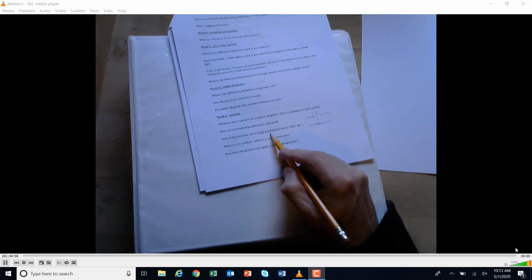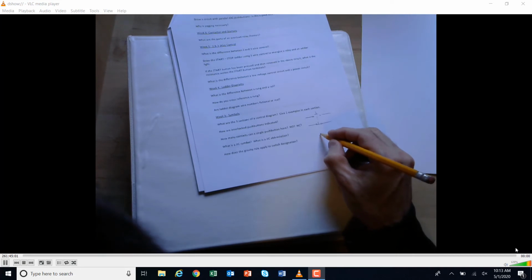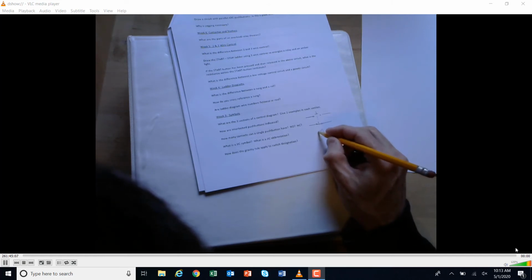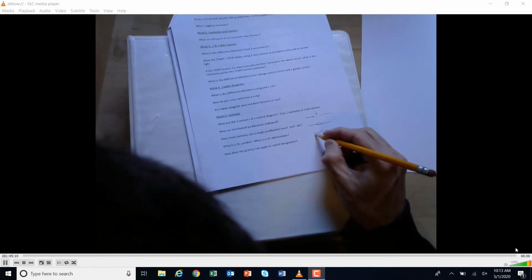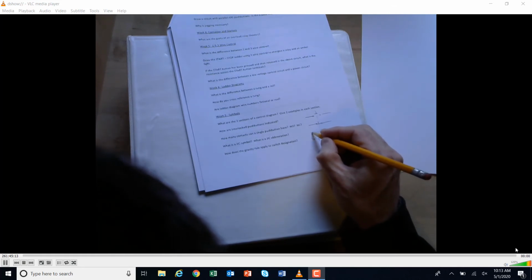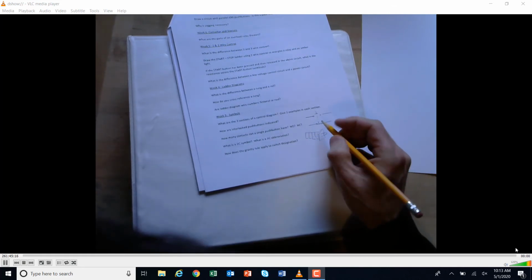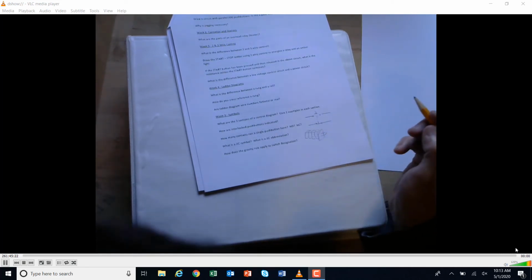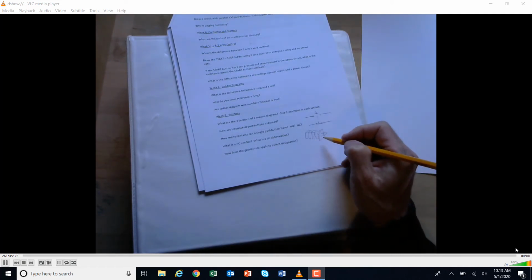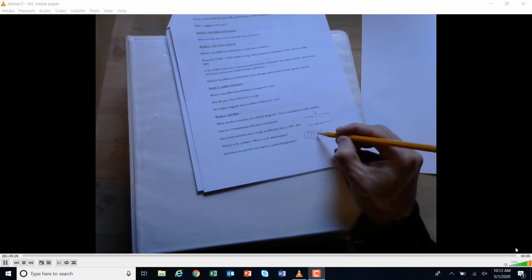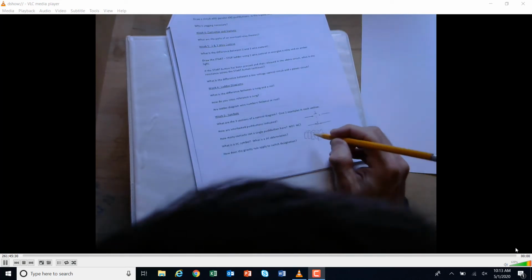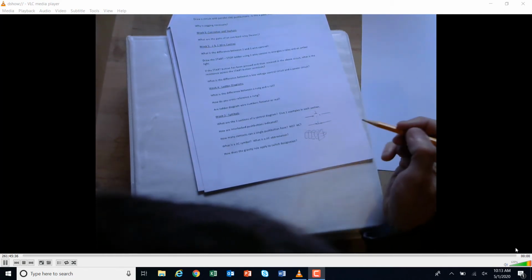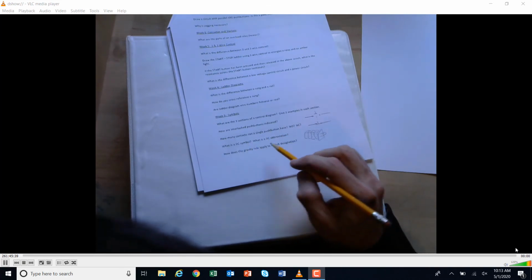Well, believe it or not, a push button can have a lot of contacts, because what you have is the actual physical push button that might look like this, right? And then on the back of it, you get a contact block with a couple of contacts. Well, you can just stack another one on there if you want, and another, and another. And they're both two-sided typically, so on this side, you could stack one this side, this side, this side. You can just keep stacking contacts, any combination of normally opens and normally closeds that you want. You probably wouldn't want to stack 1,000 or 100 or 50 or even 20. Typically you might see some of these with 2, 3, or 4, maybe at the most, but you could have a lot.